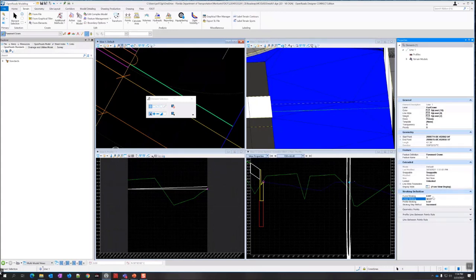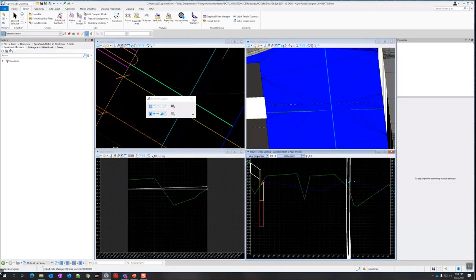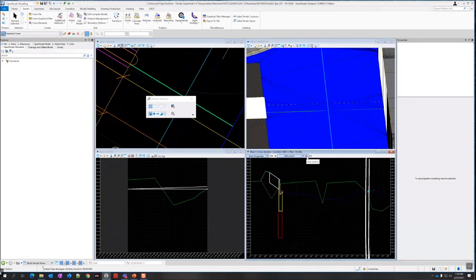Well, that's much too large. For an intersection, I'm going to set that to 5 feet. And it added a whole bunch more triangles here now. So basically every 5 feet it's going to put a triangle. And you can control that with linear stroking. And that's going to affect other things. It's going to affect linear templates as well.